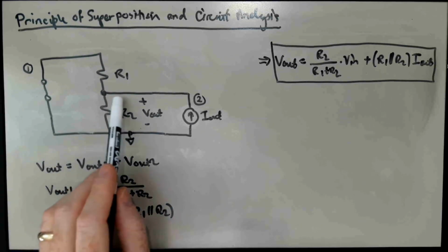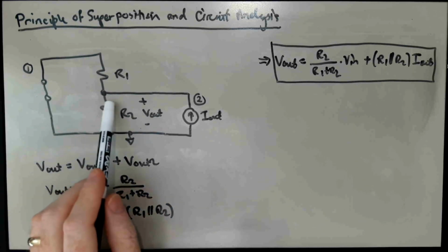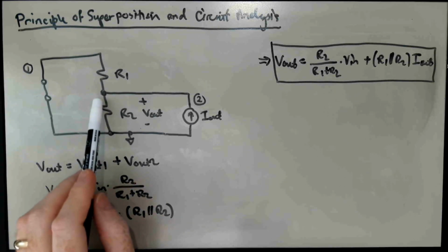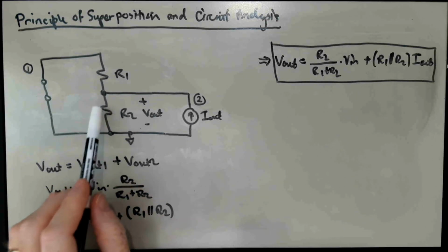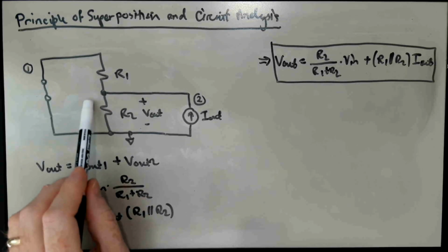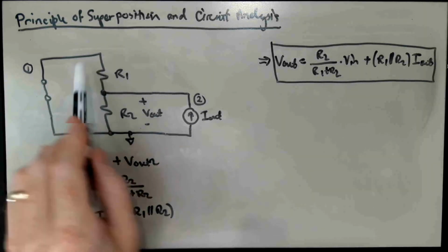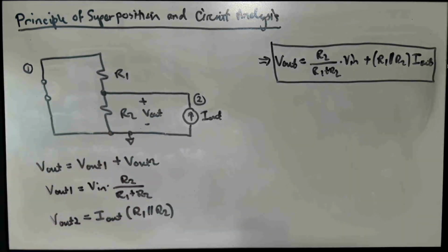So there are much better ways of creating a voltage source, like a linear regulator or something like that, that is not super efficient, but at least we're not dumping power through this other resistor here, R2. We're only dissipating power in the stuff that's up here for the most part.